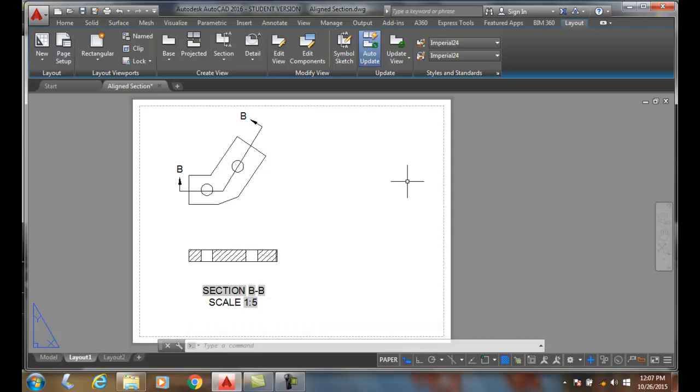So when we create a section view from an object, essentially it's because it's difficult to locate points when we're using the Viewsection command. And then the object we select will determine the type of section that we're using, and then we can actually draw our cutting plane line to create our section. It provides an alternative way to create a section view that might be easier than picking points.